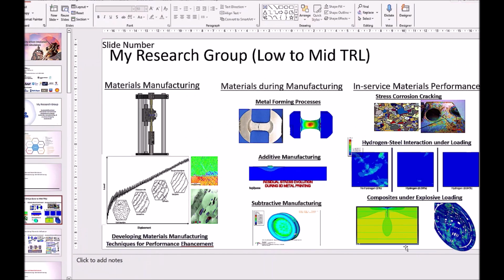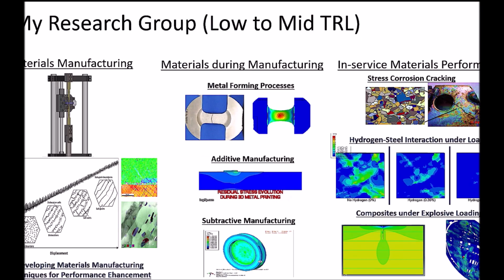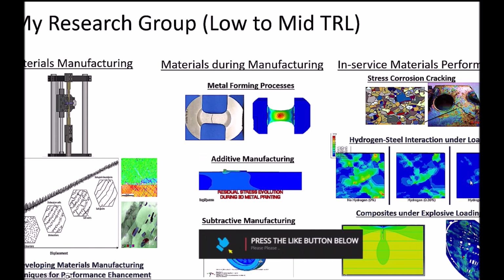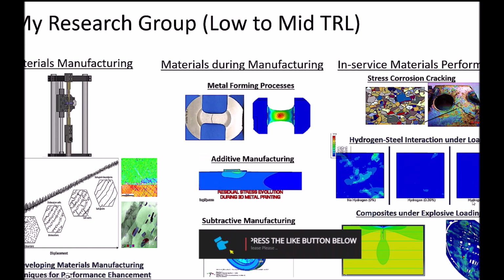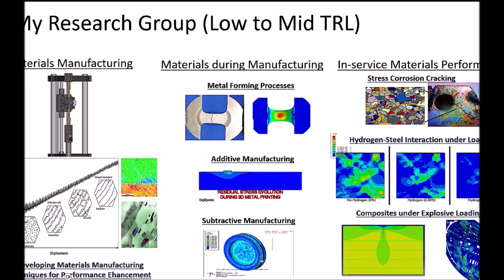In any case, you might see it here as well. This is one of the examples. We had a microstructure here, and we basically use that for this. You see these are the same microstructure with 3 different hydrogen concentrations, and the microstructure is showing a very different response. When you have 0 hydrogen, you have more ductility as compared to when the hydrogen concentration is increasing from 0.0 to 0.35, 0.64. You have a very different response.